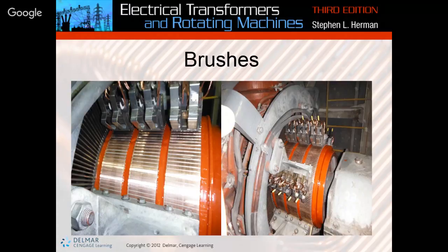So here are the pigtails that come off, and these are going to go up and land where these wires go to right here. See these big wires? These are armature cables. These are going to land on each one of these brush boxes, and the pigtails of these brushes are going to land on that same common point on the brush box. So the brush rides inside this, which is called a brush box.